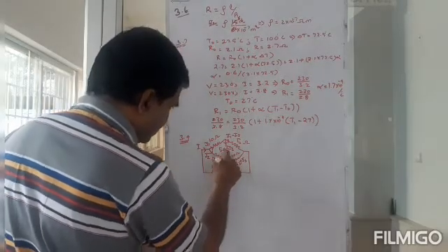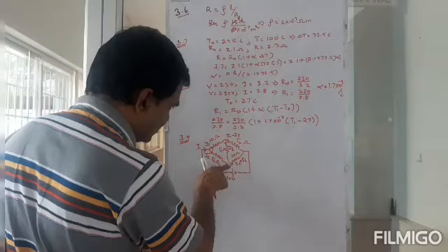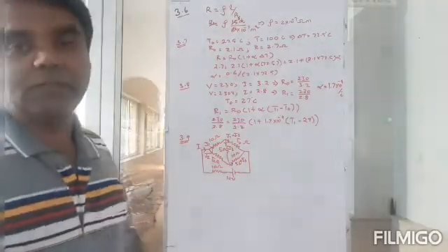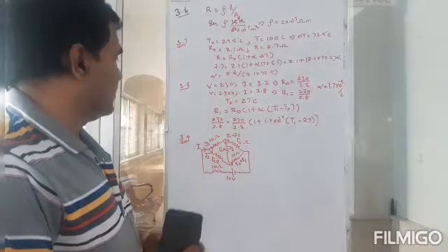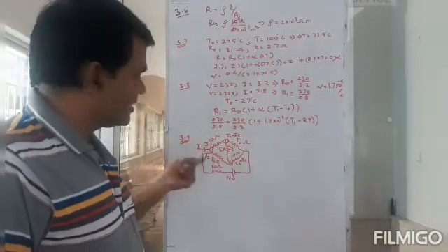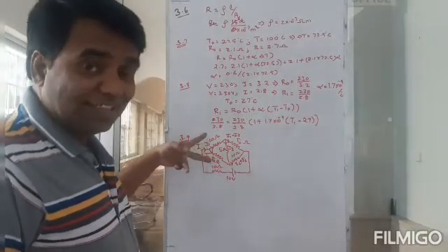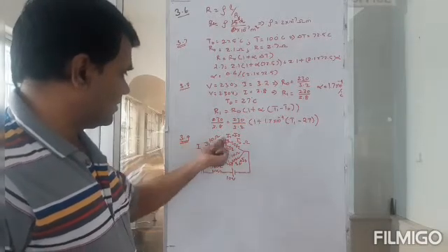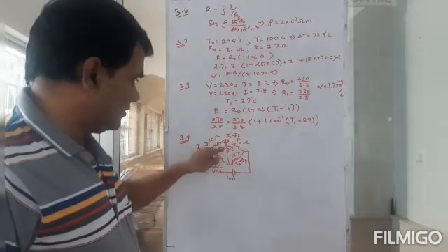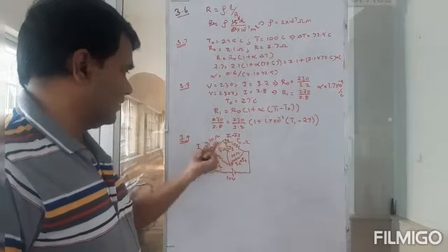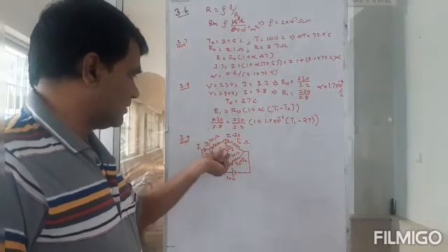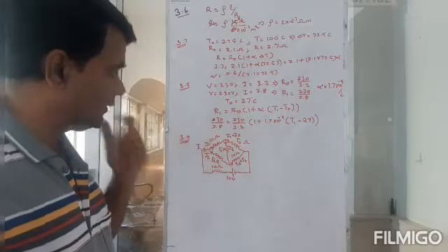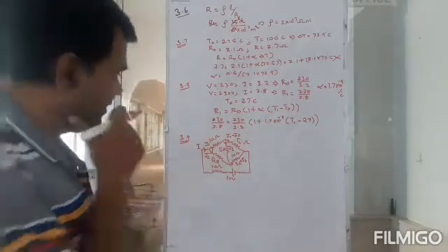I3 is coming here, I2 is coming here. So this must be I2 plus I3 using Kirchhoff's current law. At a junction, the amount of current coming in must be equal to the amount of current leaving. So here I1 is coming here, so then that becomes I3. So this must be I1 minus I3. So I1 minus I3 plus I3 will give you I1. Once I have set the current like that, what should I do?